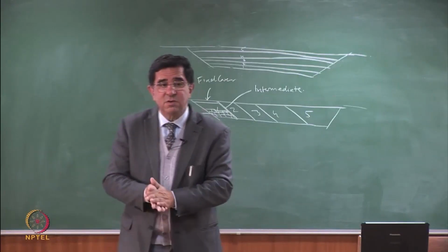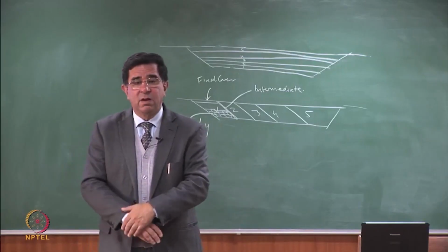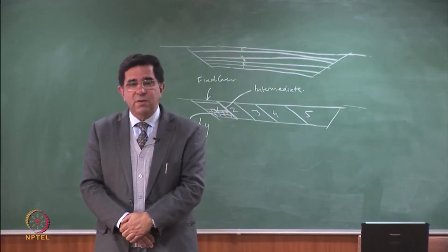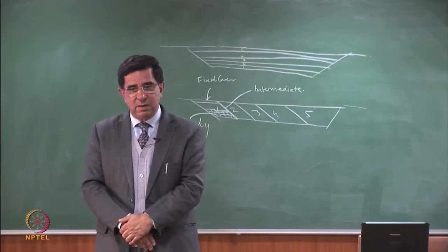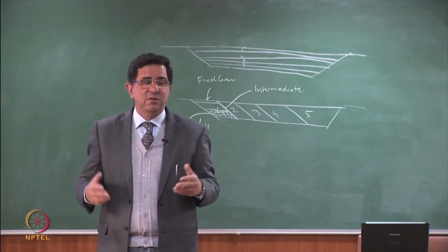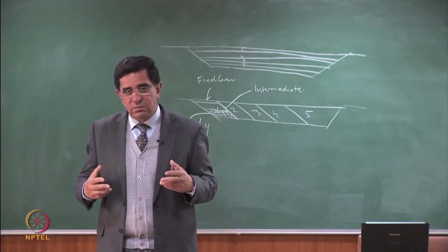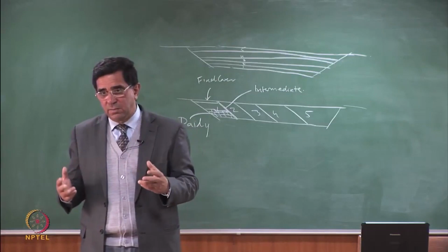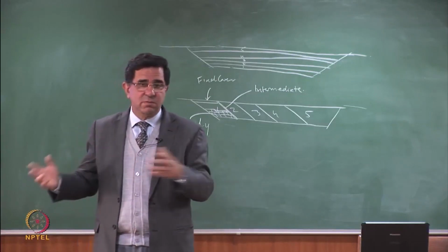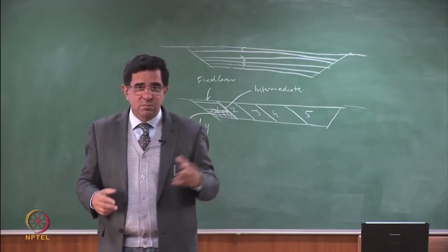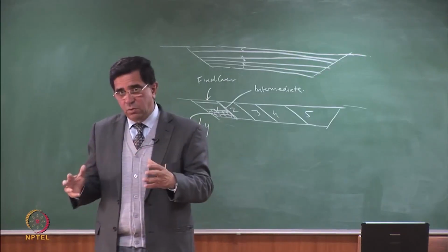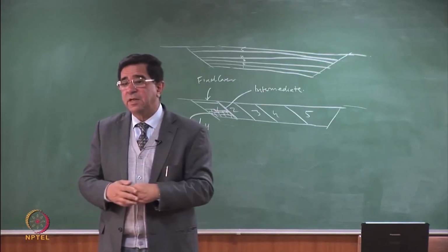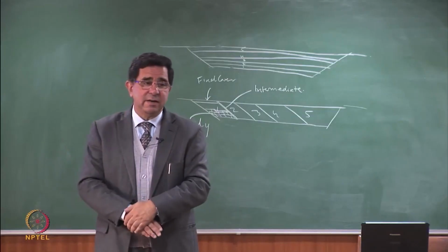Any questions, any clarifications? Sir, how can we control the fire coming out of an open dump? We will do this when we are talking of rehabilitation of old dumps. The question being asked is how do we control fire coming out of old waste dumps. Many waste dumps have smoldering fire and smoke coming out. We are going to separately address old waste dumps. At the moment we are doing design of new facilities. When we do old waste dumps, we will see how we tackle old fires, which can be deep seated because of methane burning inside the waste dump. We will take it up at that time.